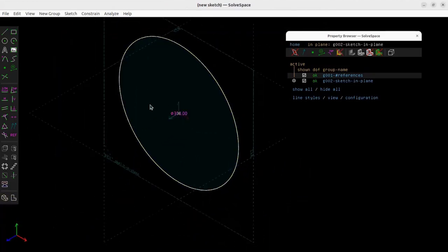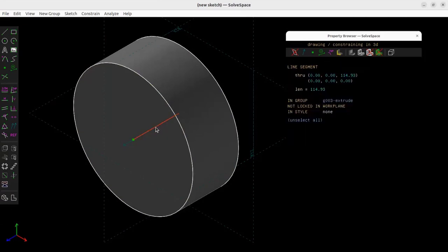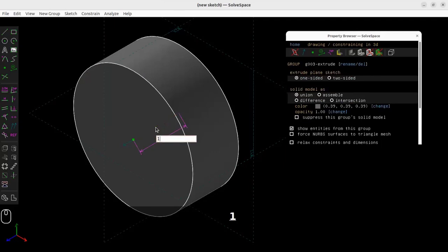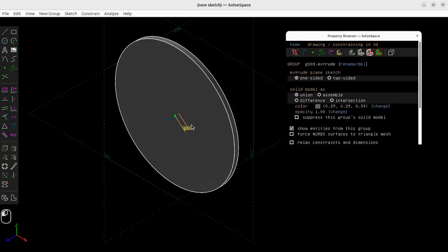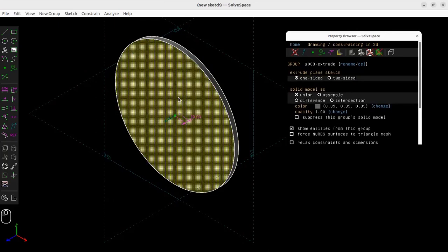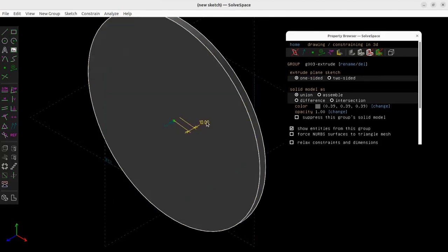And we need to extrude it. And here I'm going to enter the distance as 10 again. So 10 millimeters, that's going to be our thickness. So you always need to also measure your material. So it might be 9.8. So in the CNC week, we're going to talk more about that. And also even in the computer controlled cutting week, we can talk more about that.